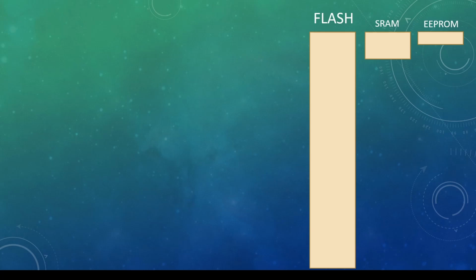The AVR is based on what is called the Harvard architecture, in which there are separate paths for instructions and data, which means that they are stored in different memories and memory spaces. In the AVR, it is implemented by the flash being the instruction memory and the SRAM being the data memory, except that the AVR also has a small chunk of EEPROM, which is another kind of non-volatile memory.